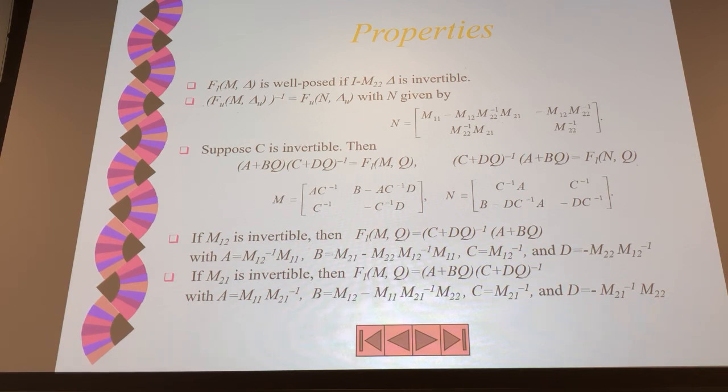Again, the reason we do this is because we made use of a structure here, the linear fractional structure. You will see in many control problems the uncertainties and the nominal systems are intertwined in this format. So this chapter is mainly about how to systematically separate the unknown, uncertain, and certain parts of the system model.